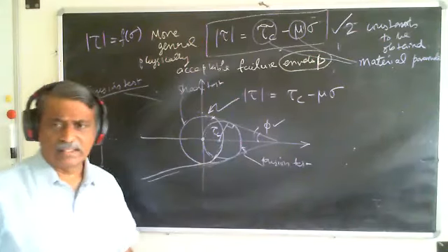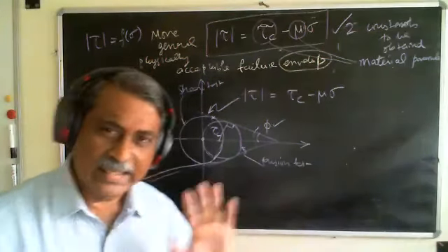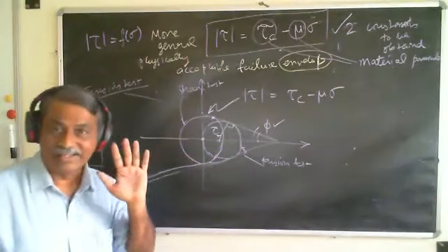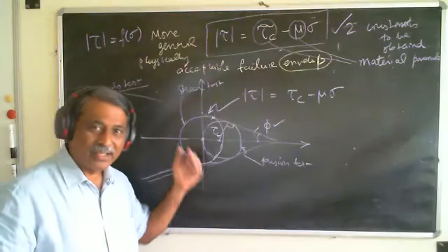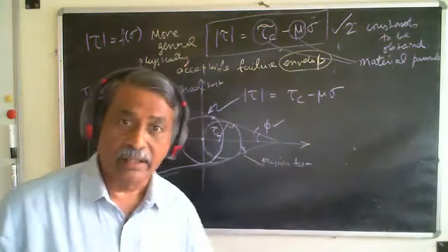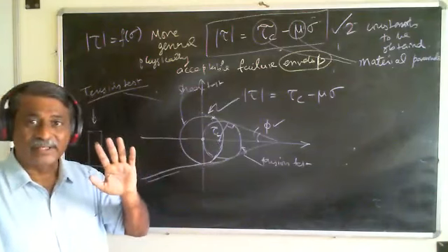You may ask, can I do some other test? The answer is yes. Basically, what I should have is two different circles. That's all. Whether it is compression test or tension test or a shear test or a combination of any of them, it does not matter, as long as I have two circles which are different from each other.